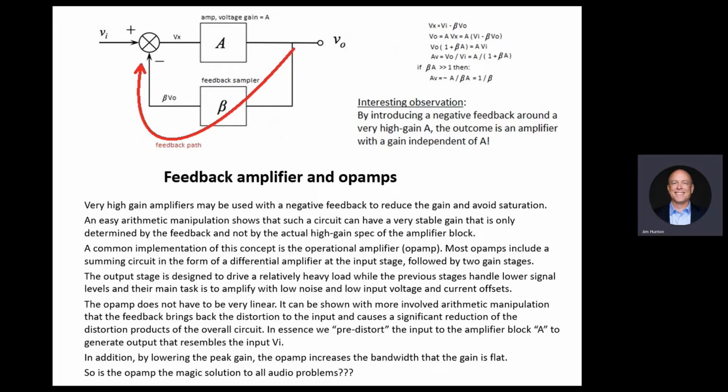I think for me, the main thing I see with designs that use a lot of negative feedback just to fix problems like distortion is they lose the natural attack and decay. You just don't feel the speed of signals. Some of them are good. Some of them are very good, and they're very careful where they apply the negative feedback. Some of them are not. So don't use feedback as a magic solution. Think about it. No free lunch. It has consequences.